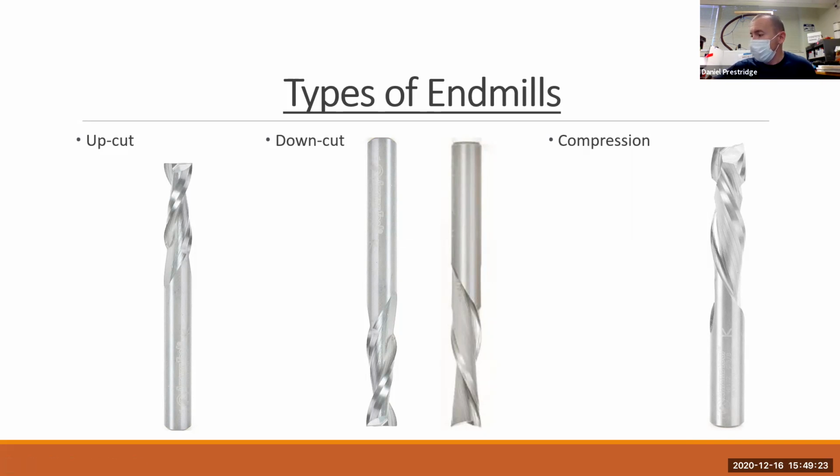The other side to that, if you're running materials like plastics or wood, I prefer it in wood, you would have a down cut. When it moves through, it pushes those chips downwards, but it also maintains the surface on top and doesn't tear out. As it moves through in a clockwise fashion, the chips don't come up and out. They follow the flutes down into the material, the substrate.